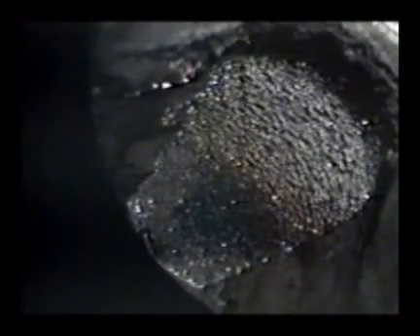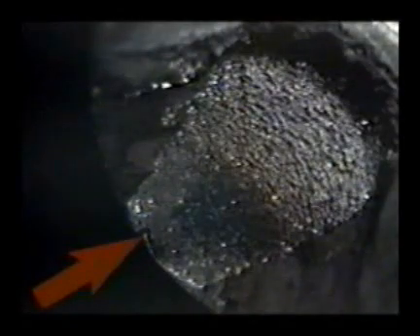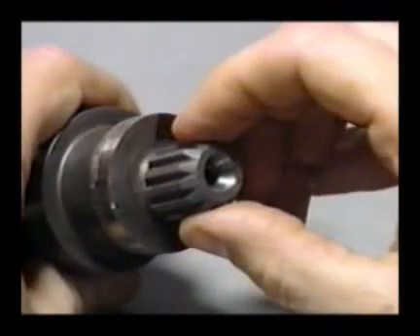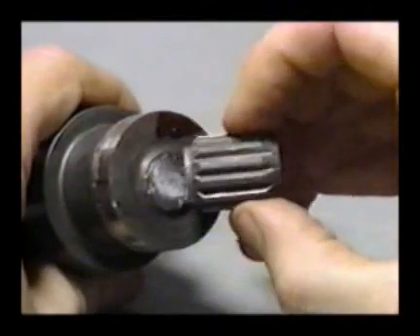Bending loads tear grains on the side experiencing the greatest tensile stress. The crack grows through the cross-section until the remaining metal shears, forming a shear lip at the final fracture. Torsion can produce either a transverse shear or longitudinal shear fracture.